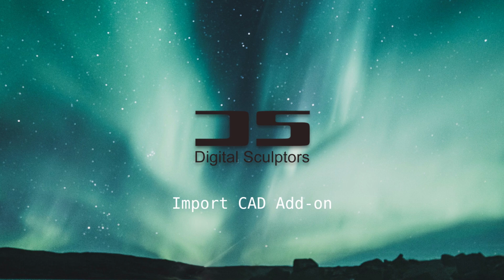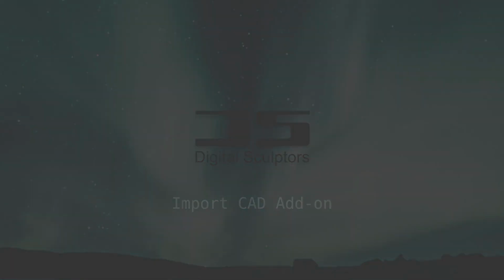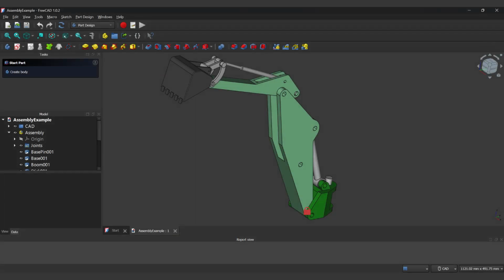Today, we will look at the Import CAD add-on for Blender. This tutorial shows how to get the Import CAD add-on, how to install it, and the general usage. This add-on can import generic CAD files in STEP or IGES format, directly into Blender.